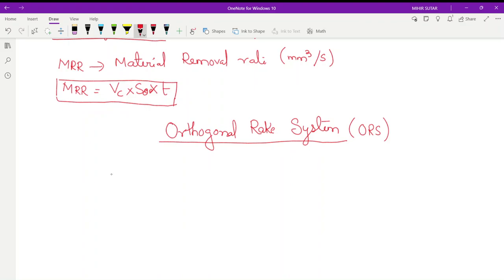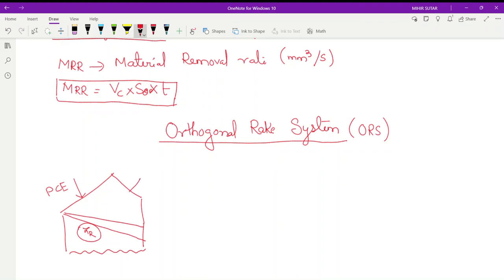So in this case, this is the cutting tool, and I have told you there are two edges. One is the principal cutting edge and the other is the auxiliary cutting edge. The principal cutting edge is always longer than the auxiliary cutting edge. This is the reference plane pi r, as it is always perpendicular to the velocity vector VC, and the Z direction always lies in the direction of VC. This is the principal cutting edge, PCE, and obviously this side is the auxiliary cutting edge of the tool. Okay, now regarding the plane.